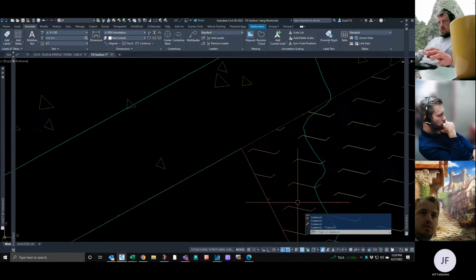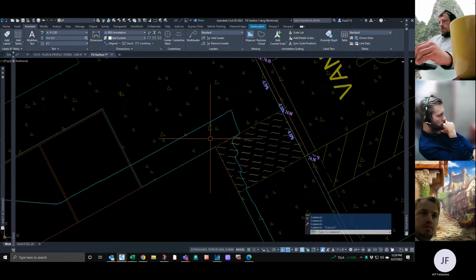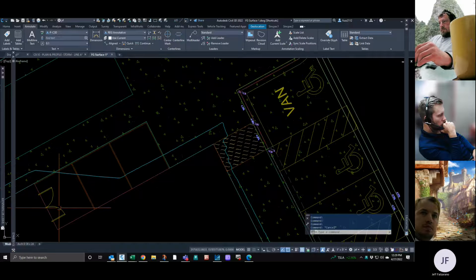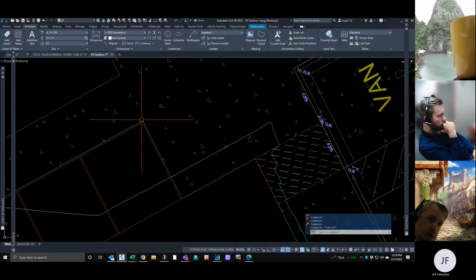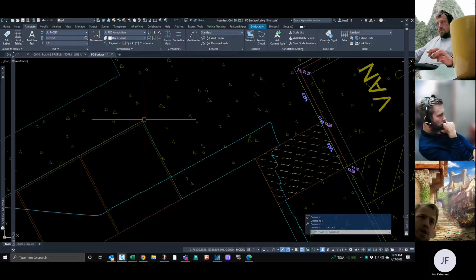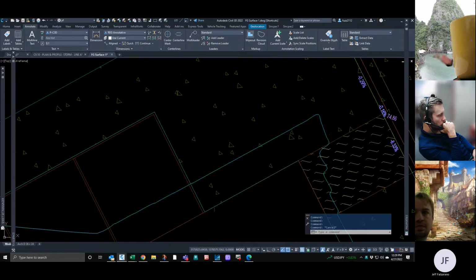Same way in this direction. And the way I do it is because this door wants to be at finished floor, but then you are grading away from this building at 1.8. So yeah, you would just drop a feature line right here, coming down at 1.8 to that corner.